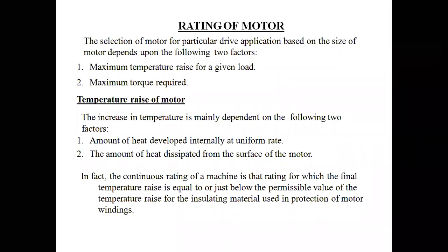So based upon your type of supply, you are going to choose the motor. Based upon your particular applications, you are going to select the motor that depends upon the size of motors. So how are you going to select this size? It completely depends upon two factors, that is maximum temperature rise for the given load and maximum torque required.